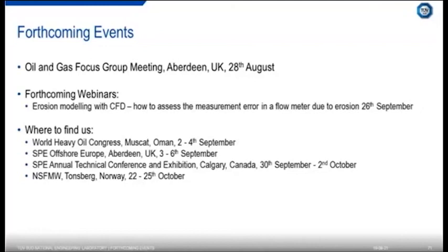Well, I'm not going to give a shameless plug for NEL software here, because you'll get the same error messages. The problem isn't you, it's the hydrogen. Hydrogen is a very difficult substance for calculating properties of, for equations of state for mixtures. Equations of state are written in terms of reduced variables, which make use of properties of the fluids called the critical properties.